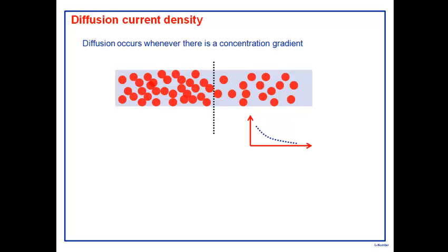So that's another source of current without any application of electric field, if I have a concentration gradient. If I have more electrons here, fewer here, this is what it shows. So if I have an electron density that is higher here and then decreases, I have a concentration gradient, and I will have a current. So one doesn't need an electric field to create a current. Current can also flow if you can create a concentration gradient in electrons. And the way we model this is, the flux of electrons that go from left to right will be equal to minus Dn, the diffusion constant, dn by dx.